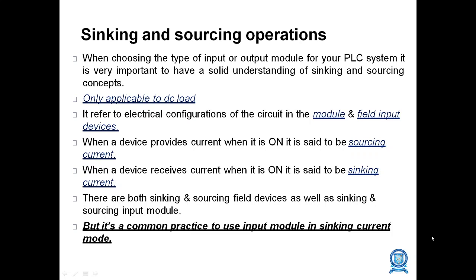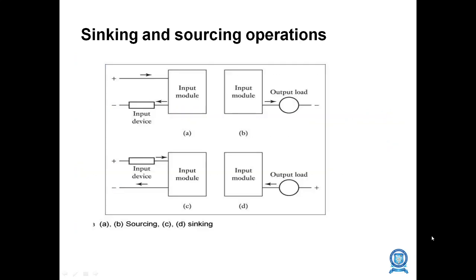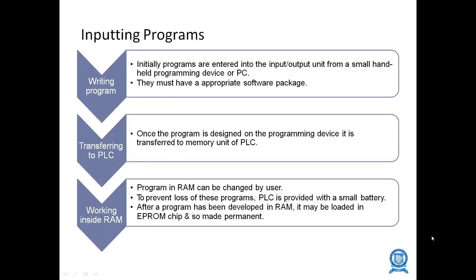There are both sinking and sourcing field devices as well as sinking and sourcing input modules. The common practice is to use the input module in sinking current mode. Sinking and sourcing operations are given in the diagram. The first one is the input module, and the input module output load is shown with the input device.